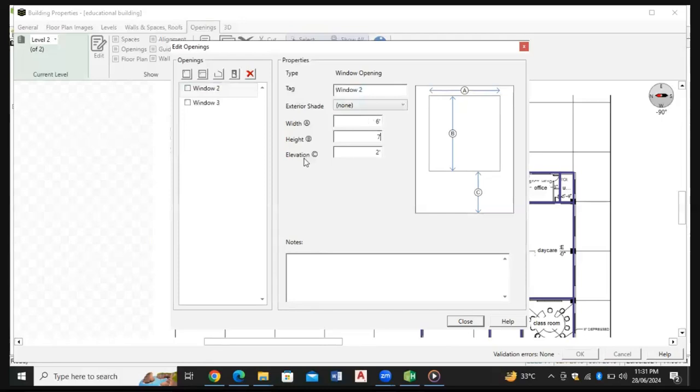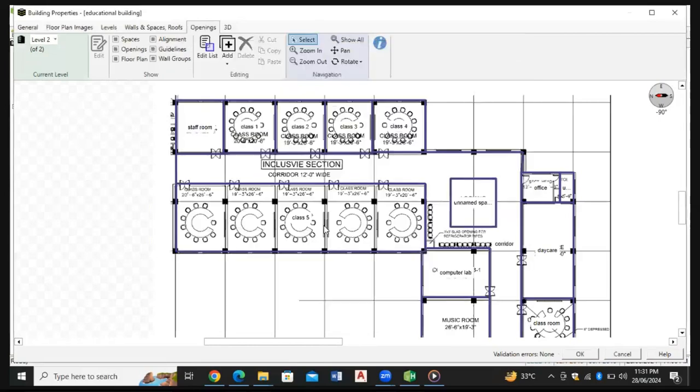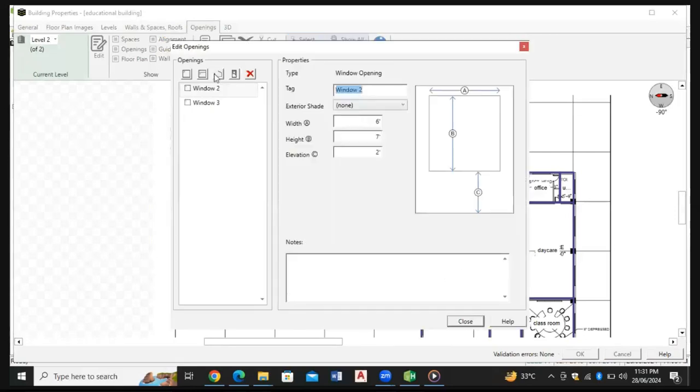And here is one more advanced thing in HAP 6.2, like I can change elevation on every window I create. Here I have an elevation of 2 feet, and if I go to window 3, it has 4 feet width and 6 feet height. So I can change its elevation to 3 feet. So I always have the option to change elevation on a building. We know that not all the elevations of windows are the same from floor level. So here we can change it.